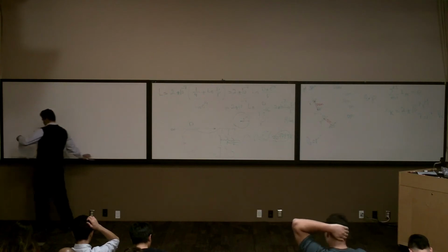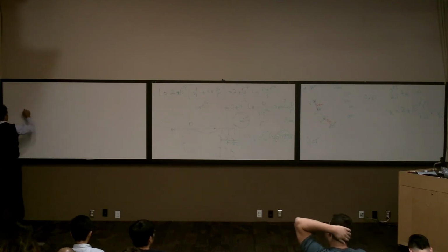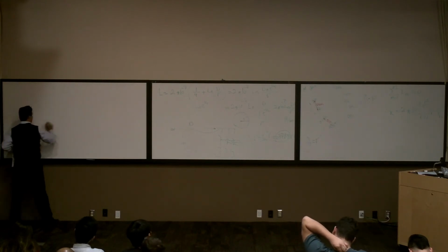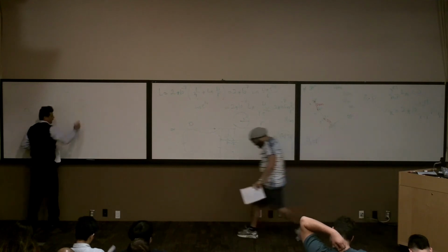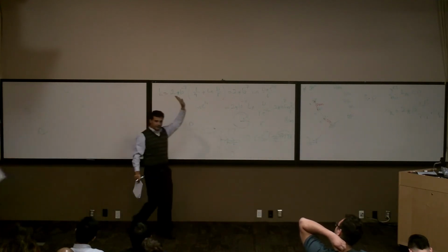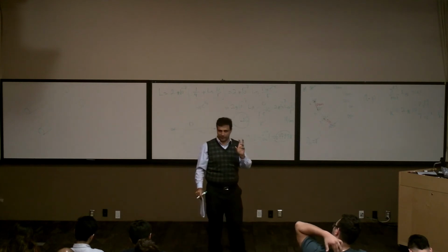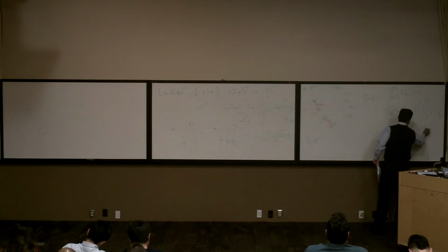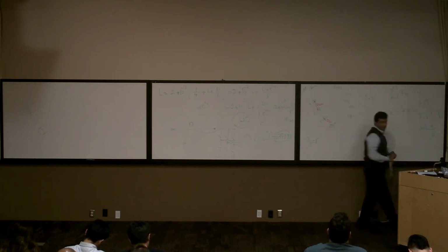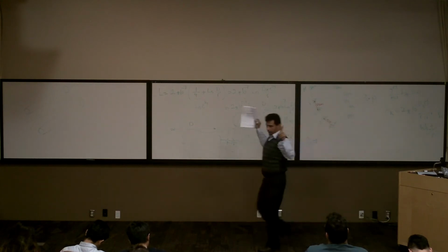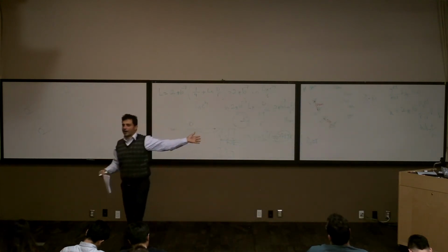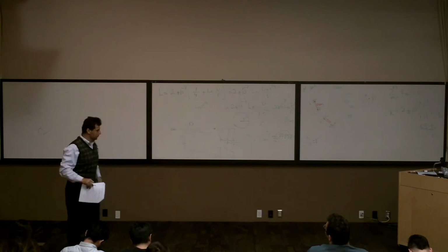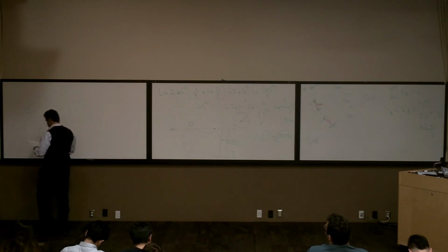So, now we have this system. I have a conductor X and I have a conductor Y. Whatever I'm calculating is per unit length. For example, this one is going to be Weber turn over meter. Just keep in mind, I'm calculating this for 1 meter of the cable. If you have 100 meters, you multiply it by 100, and if you have 1 kilometer, you multiply it by 1,000.